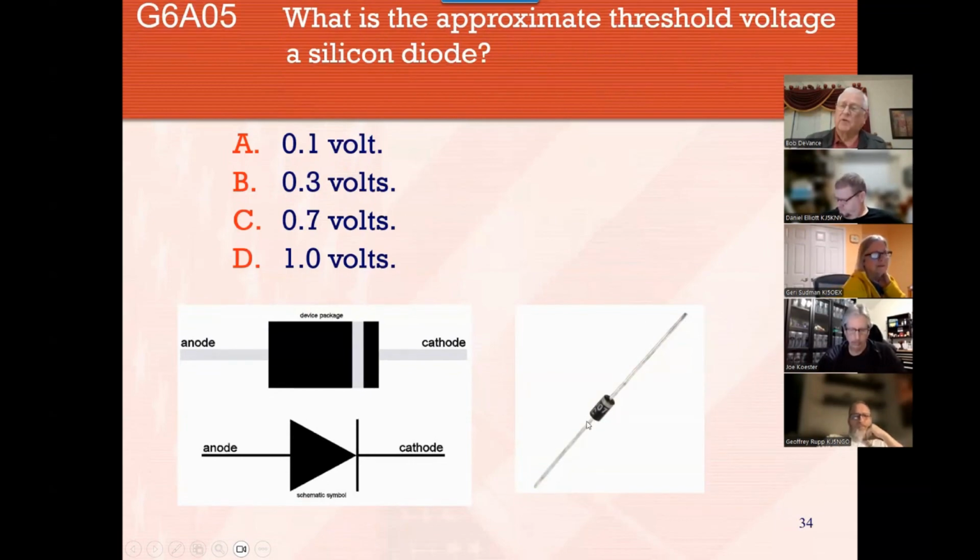You notice this has a lot heavier encapsulation. These little diodes come in higher voltages, higher amperages, you name it. That one looks like it's a 1N4007, because you can see the 07. The 1N4000 series diodes, 4007 is a 1,000-volt peak diode. 1N4000 is a 50-volt diode, and they conduct 1 amp. So they're heavy-duty diodes compared to the germanium, but they do have a much higher forward voltage, which is 0.7 of a volt. Germanium 0.3, silicon 0.7.